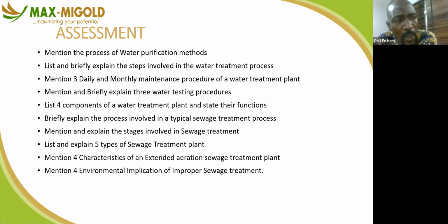Then the second thing is, I always tell facility managers, when you are taking over a facility, you should always request an as-built diagram of that particular building. The as-built diagram will tell you the area where the piping network has been laid. At times water could be leaking at point A, and where the water will come out is point B. If you don't have an as-built diagram telling you where the leakages pass, you have to break the whole entire floor looking for where the leakage is actually coming from. So that's why it is always required.